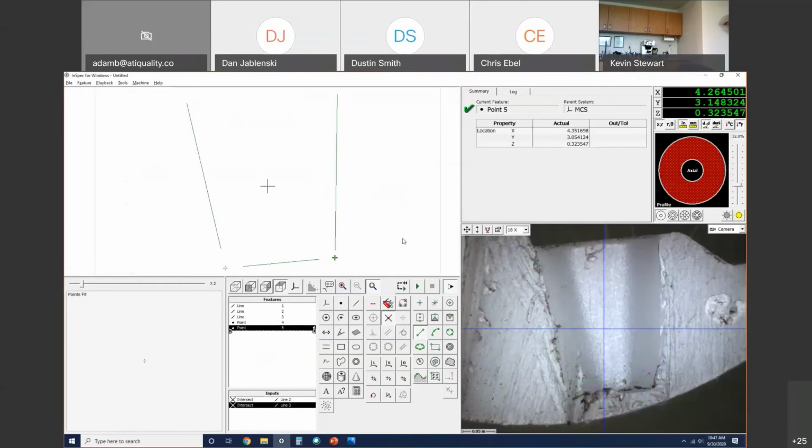This is where I'm using this example just to explain to you guys how getting creative with your construction icons and your dimensions will help you out. If you're looking at a feature that you have no idea how to measure, don't forget about the construction icons.